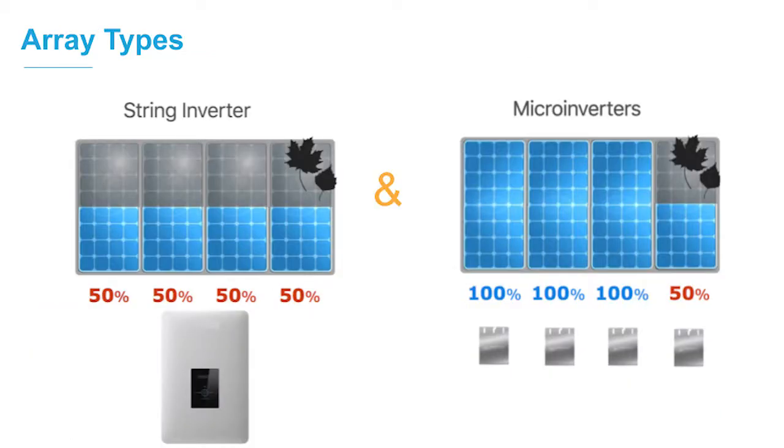If you remember from before, the solar panels collect the sun's energy as DC, or direct power. But most homes in the US run on AC power, or alternating current power. That means the DC must be inverted to AC in order to be useful to the home. There are two types of inverters, the string inverters and microinverters. Think of them as connected like Christmas lights. If you have a string inverter and one panel gets shade, it can potentially knock out the other panels that are not shaded, much like a string of Christmas lights and a missing light bulb. If you have microinverters, then if that same panel gets shade, the rest of the panels are still able to function normally.